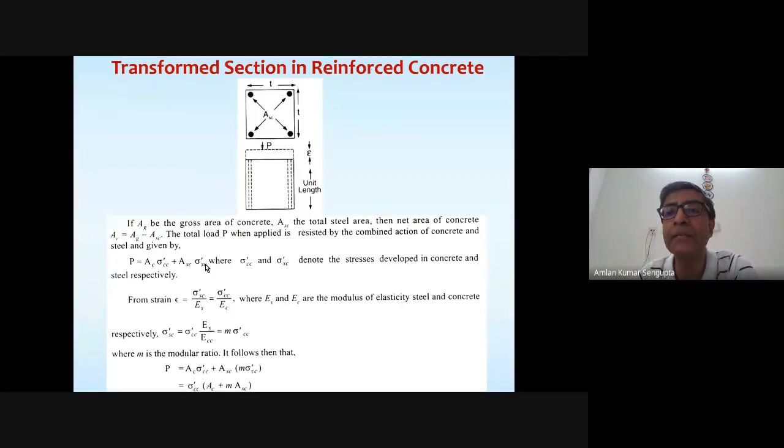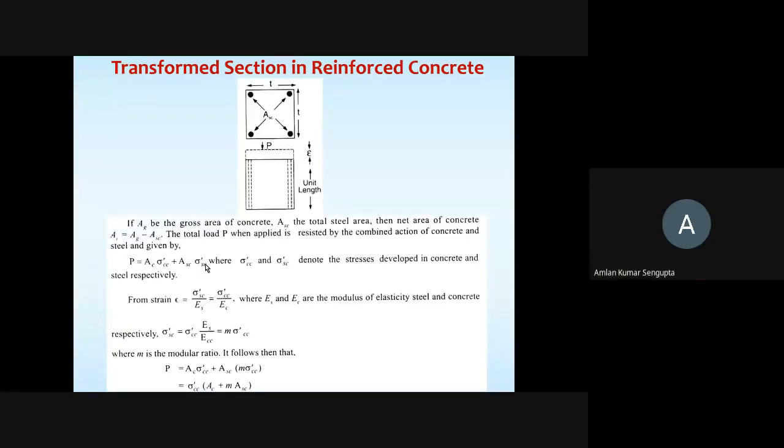The third principle is called the constitutive models, the constitutive relationships, which relate the stress in each material with the strain. In this particular case, they're all considered to be linear elastic, in this working stress method, and then we are defining the modular ratio and all. But in essence, we have 3 principles here. First, equilibrium of forces. Second, compatibility of strains. And third, the constitutive models for the materials. Any questions?